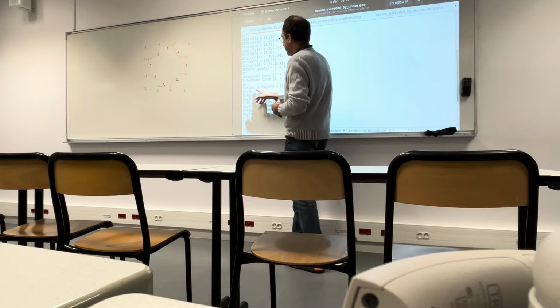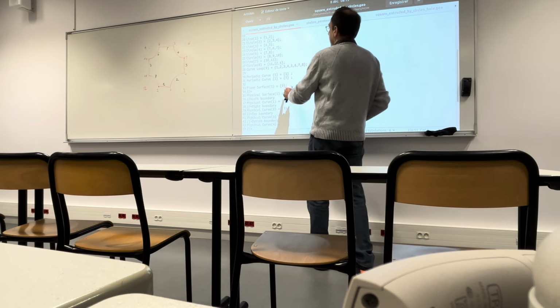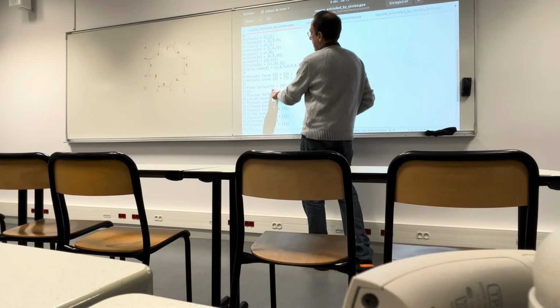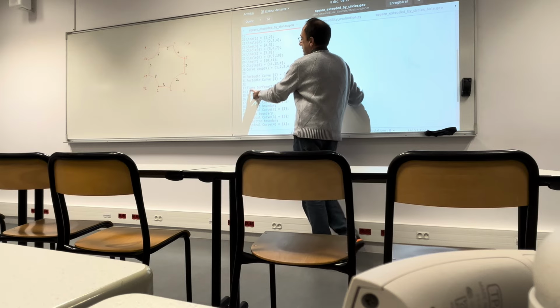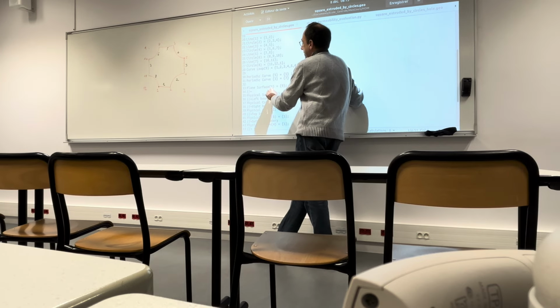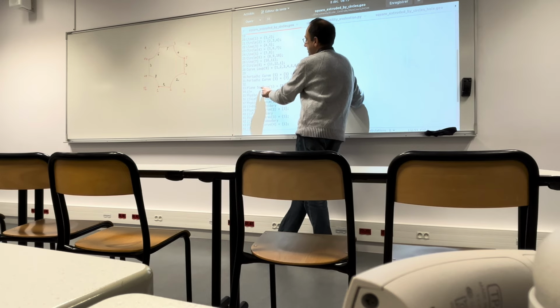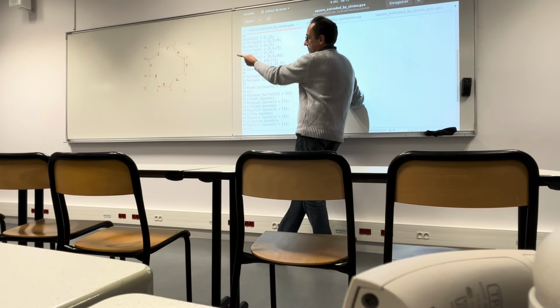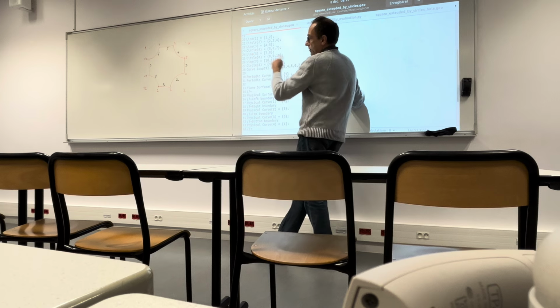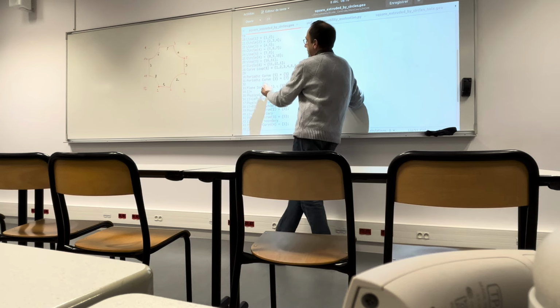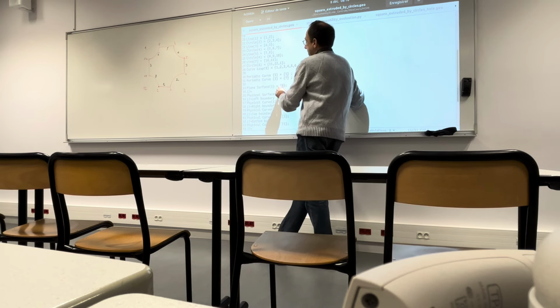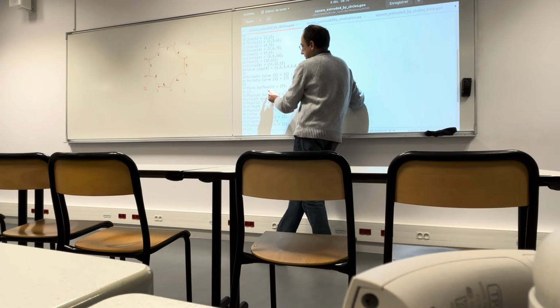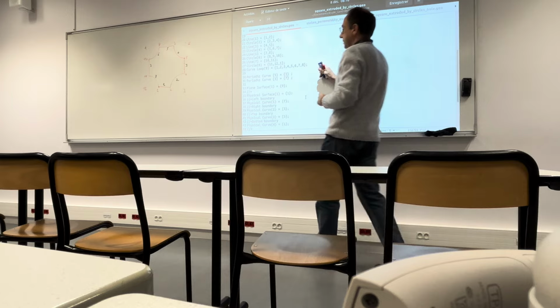One surface, plane surface 1. In fact, this means that when you specify the plane surface, here you are indicating what the boundaries of this surface are. In this case, the boundary of the surface is just the internal part of this domain, so plane surface 1 is just the domain bounded by curve 9. This is the meaning of this statement.